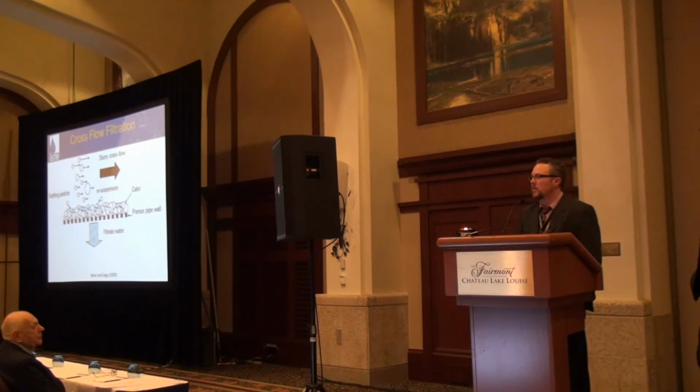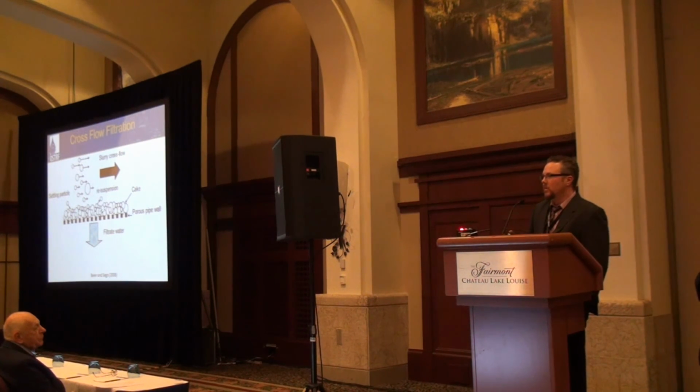What is the water quality of the filtration water? It's the same chemistry of what's in the whole tailings that's going in. So whatever's coming out of the extraction plant. Our target was not to add chemicals, but to get the dewatering rates that we needed, at least based on the data I had, we had to add flocculant. So the only thing we're changing is adding a flocculant to the water.